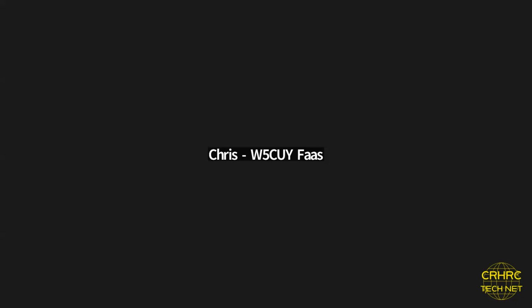I don't understand on the Fusion side, but the pseudo nodes live inside the server, the same place that the hub node is registered. So when somebody keys up on Echolink or on the All-Star side of things, it's pushed through the hub out to everything else that's connected to the hub on the All-Star side. There's magic, like Bill and Thomas were talking about, that handles translation between the Yaesu language and the analog language. That bridge, the translation part of it, is handled through that pseudo node number in the server itself.